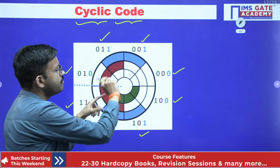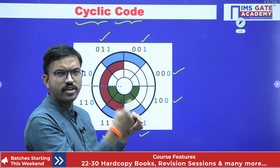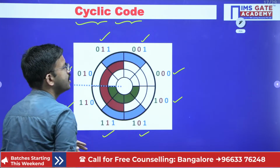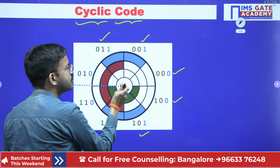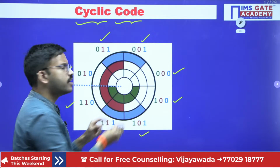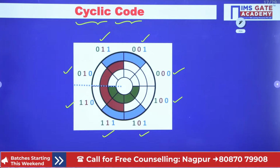Whenever any mechanical device is taking the rotation operation in circular fashion, either clockwise or anti-clockwise, at that time if you are using the gray code, with the help of gray code you can find the angular displacement or you can find the position of that particular shaft. So this is the real time application of the gray code.